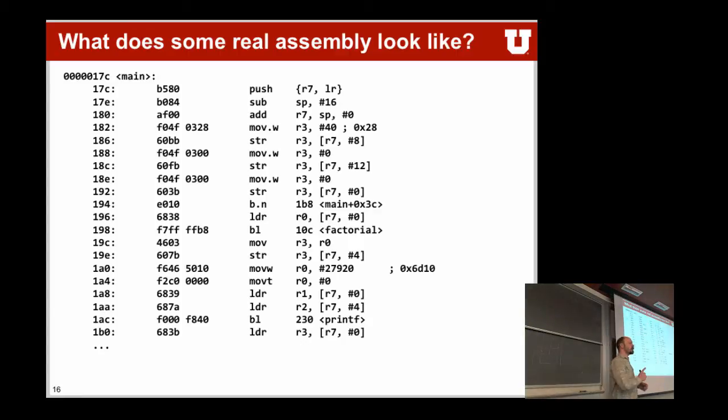Not entirely sure though. It could also go the other way around. And we will actually talk about the stack and push and pops in later sections, because there are a lot of things that happen automatically on the ARM. Remember when I talked about how the ISA can help the binary interface and function calls? This is one of these things that we will see in certain branch instructions. The microcontroller actually does a couple of pushes and pops for you, just automatically, by executing a certain assembly instruction.